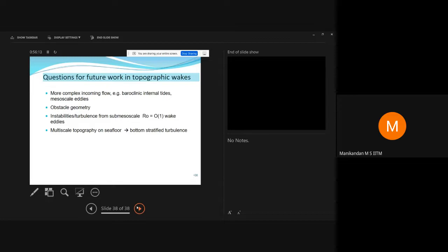But what happens, and the reason, so we've had quite a few students working with me and evaluating several aspects of this problem, is that as the fluid develops, the vortices become larger, so then the time scale of the vortices, and also the wake effect velocity decreases upstream, right? So then the characteristic time scale of the vortices changes, it becomes larger and larger. So eventually you're pretty much guaranteed, if there is a wake and if there is stratification, eventually the picture changes from three-dimensional turbulent wake to whatever stratification goes to.